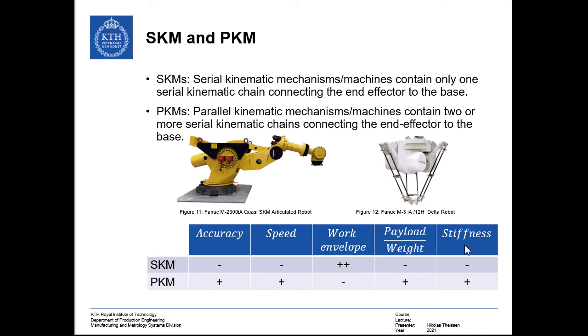Stiffness is not only an important characteristic when it comes to the machining of parts, but a higher stiffness usually helps systems to have higher first eigenfrequencies, which usually also makes the operation and control of systems simpler.